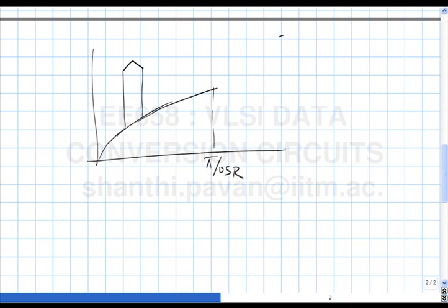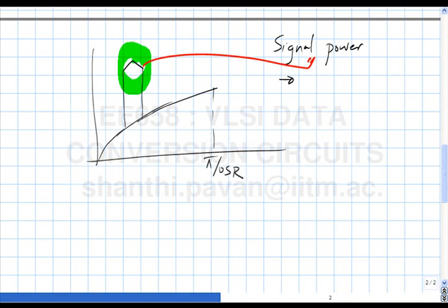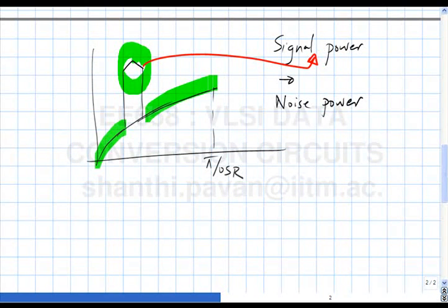So to find the signal power, what should you do? You add these three bins. No, you don't add the logs up. You add the squares of the FFT coefficients. Okay. All right. And to find the noise power, what do you do? You add up the powers in all these bins, okay.